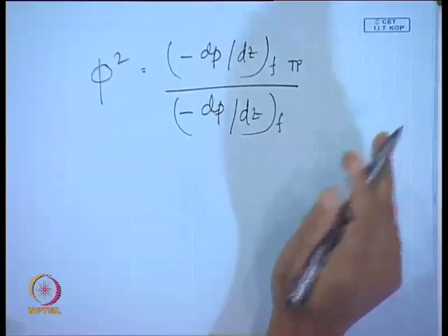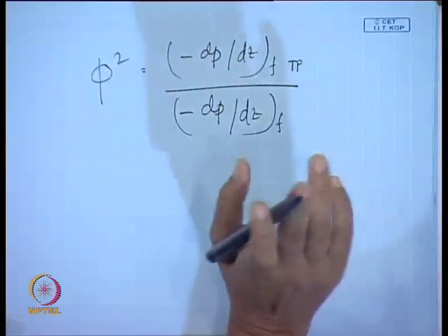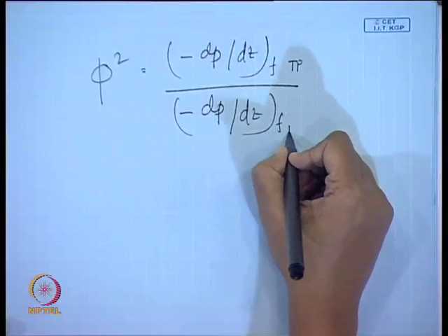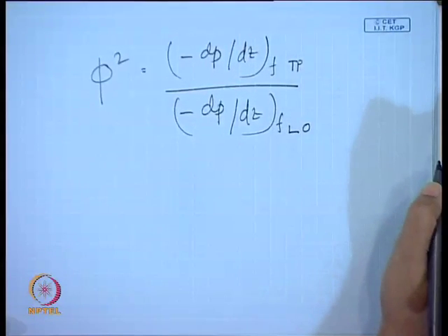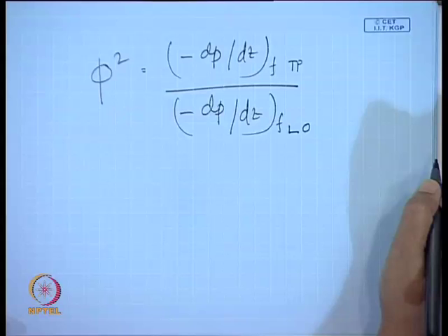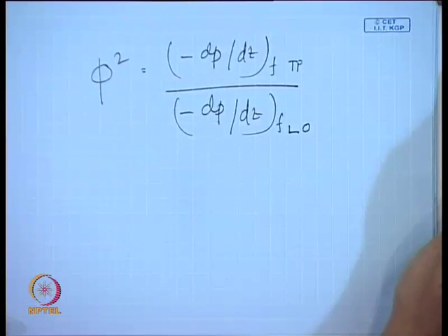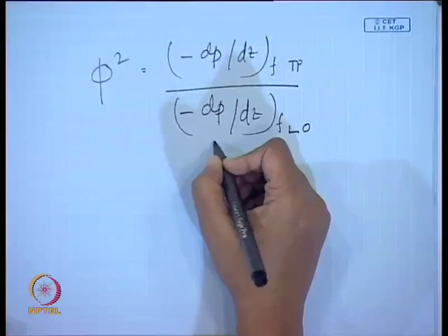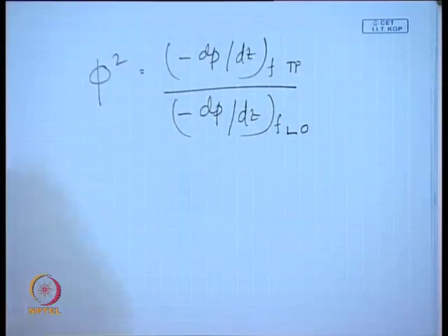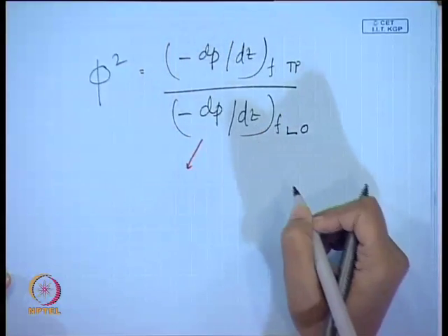Now, remember in this particular case, we can define 4 different correction factors. How? One is when the entire mixture flows as liquid. Do you get the point? Which we have been doing so long. When the entire mixture flows as liquid, what is the expression of this frictional pressure gradient?